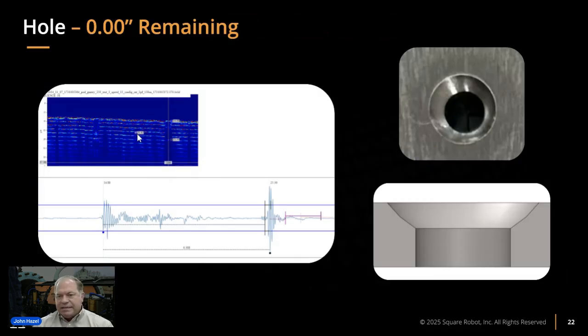And then one of the next things that I was always curious about is, what happens when you see a hole or when you find a hole? Do we ever find a hole? It's kind of one of those things that, being in tanks for 25 years, I've just always wondered about, and it happened to be part of our test here. As you can see, we don't get any return on our A-scan, or very small return based on geometry here.